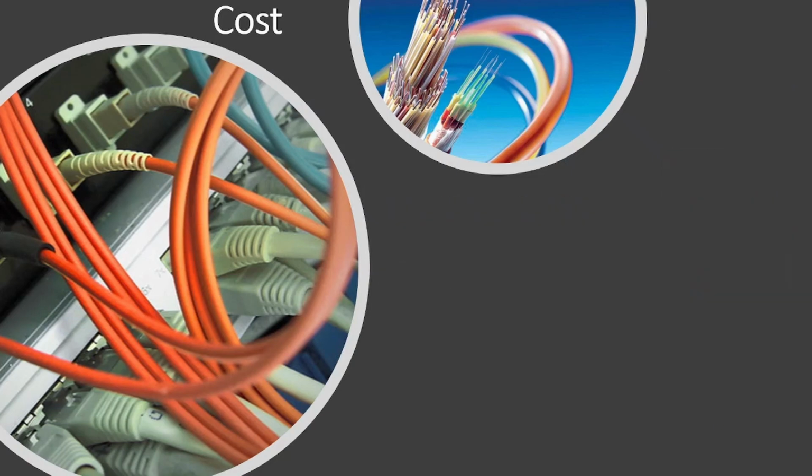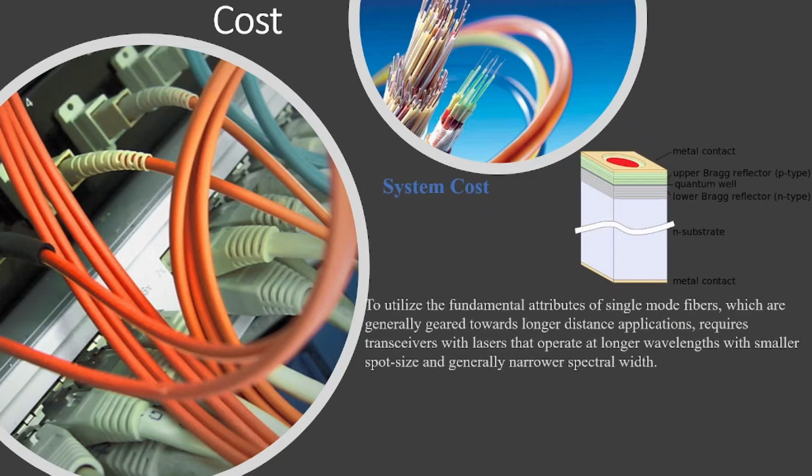And regarding their system cost, to utilize the fundamental attributes of single mode fibers, which are generally geared towards longer distance applications, requires transceivers with lasers that operate at longer wavelengths with smaller spot size and generally narrower spectral widths.